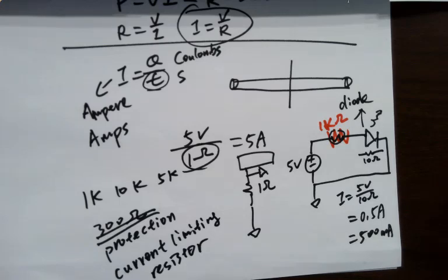So what if you put a 1K resistor and it's too dim? What do you want to do for that? Use a lower resistor. So what's the resistance you want to use? How many volts do we want to send to the LED? We usually don't consider that. How many amps? How much current? Current, right? So just look at the paper. What's the range of the LED you're going to use?